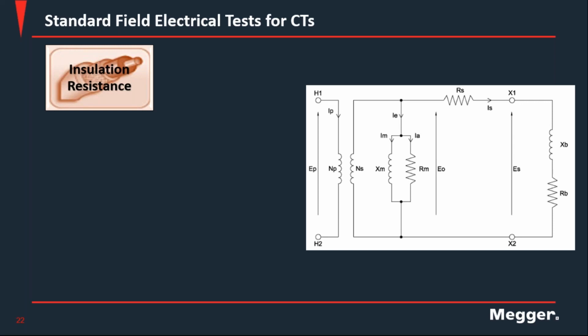All right. Daniel, can the insulation test cause remnants? Thanks, Mike. There's certainly a possibility. Remember, as a non-written rule, anytime you are using any DC-based method for any measurement, there is a possibility that you can have some remnants in the core of the CT.